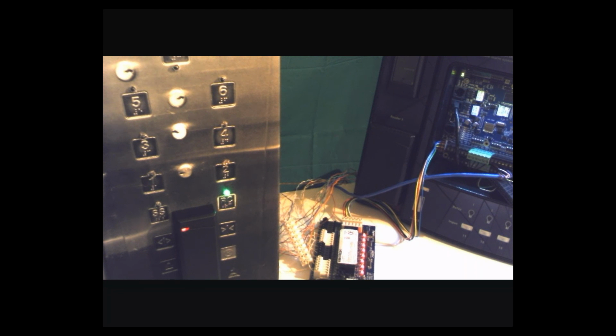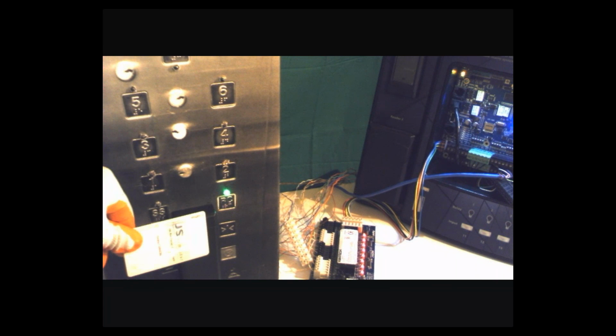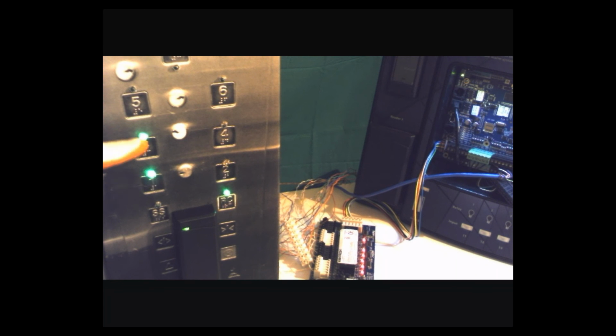That's it. And remember, the way we designed that elevator control, the lobby, oh, the card was too close. The lobby, we set it to always be available. So that's why we only have those 8 other floors. Now let's make a test again. We created 2 users. We have 8 floors. One user is always valid for all floors, meaning when he comes and swipes, we have all the floors come up, and we just select. The other user, when he comes inside that cab, can go to the lobby without swiping because the lobby is enabled, or he can swipe and his access gives him 1 and 3. We can play like that with all the possible